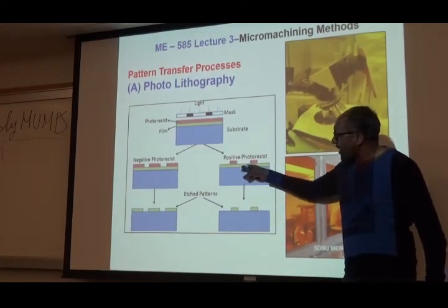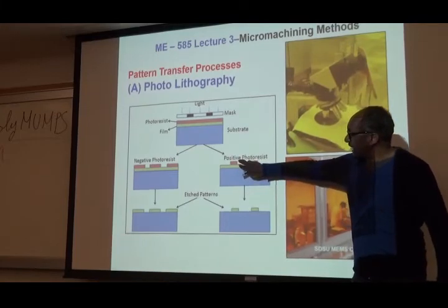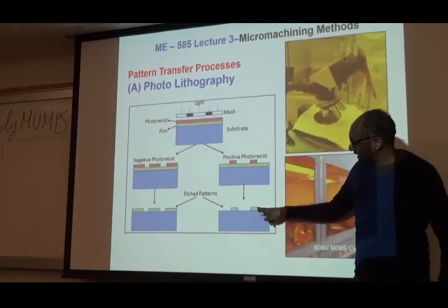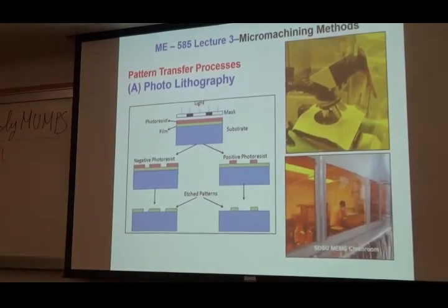And then once this is washed away, I have only this guy left, so I wash that part. At the end, what do I have? I have the green part, selectively etched. Does that make sense? So at this point, the photoresist is removed. I'm ready for the next layer. So then you start another series of lithography.